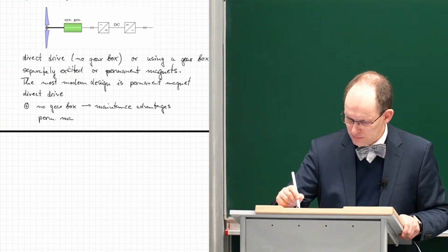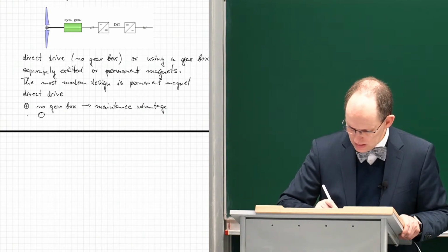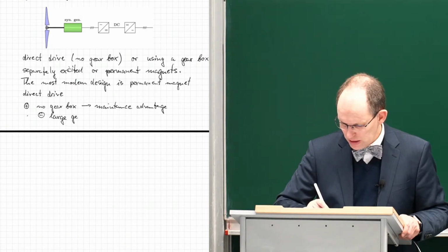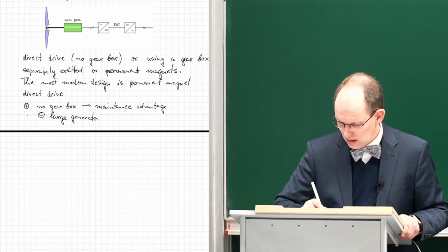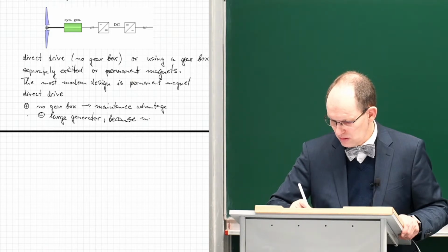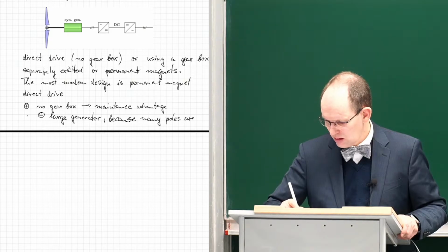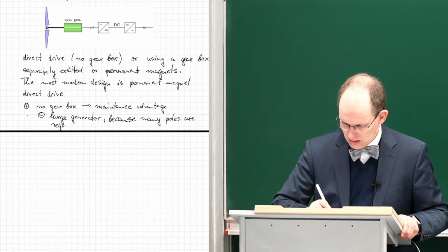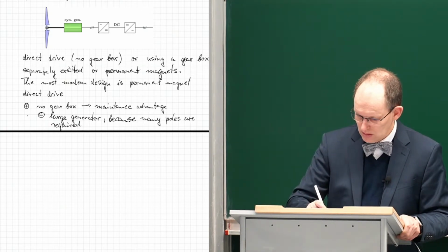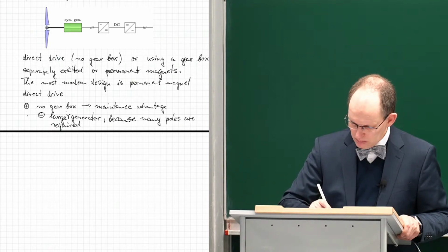I should have written no gearbox. But the downside is a large generator, because many poles are required. It also makes the generator more expensive. Large generator, large and more expensive.